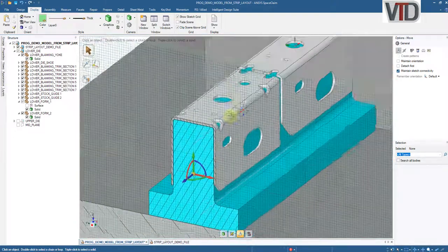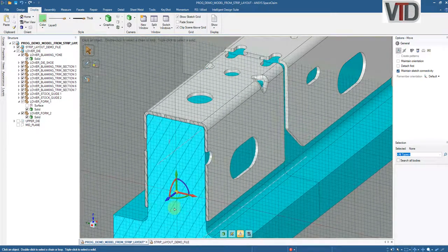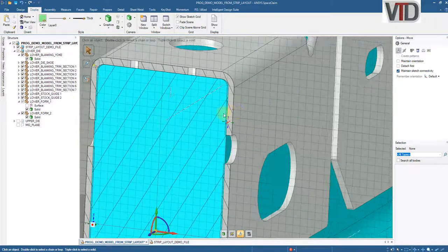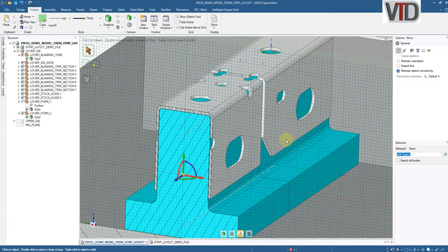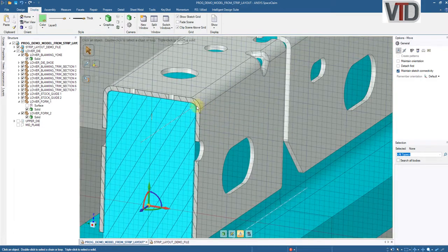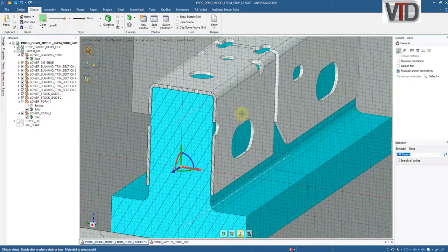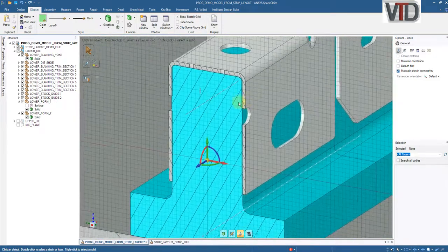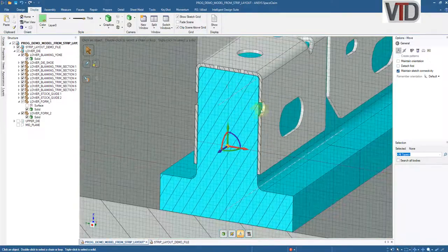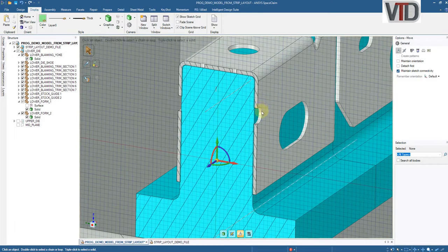So what was done here is in the first form stage, they're flanging down 20 thou wider and then wiping it tighter in the second form to allow the flange to come around. Because when you wipe this flange down, it's going to be sprung open. So by wiping it and then re-wiping it in a tighter, narrower width of the part, you're going to get that effect of continuing the radius around as you wipe. But what that's done to our form stage here is it's made it so it doesn't work for the second form.